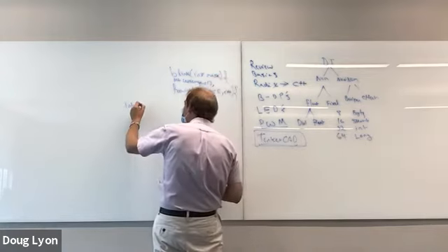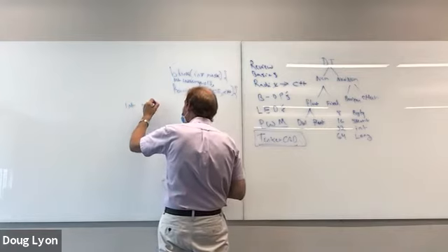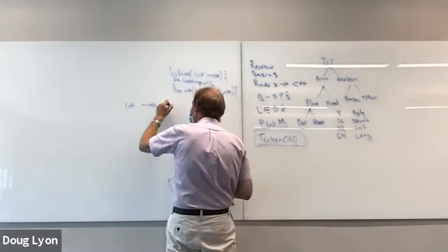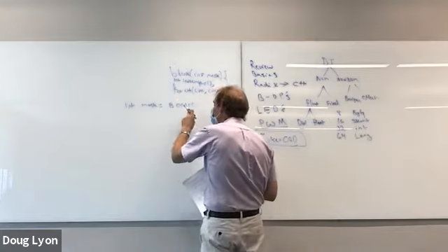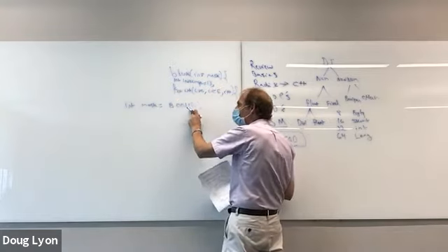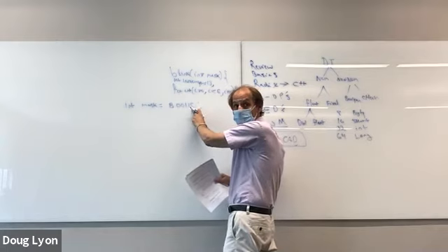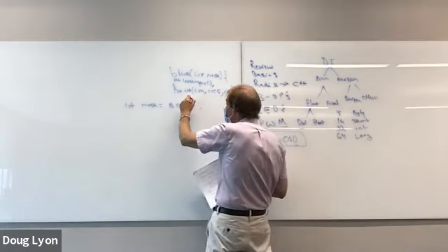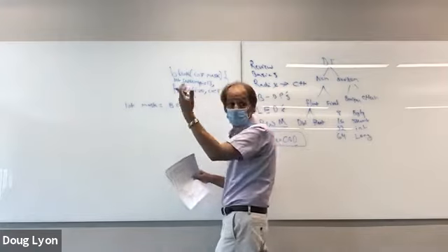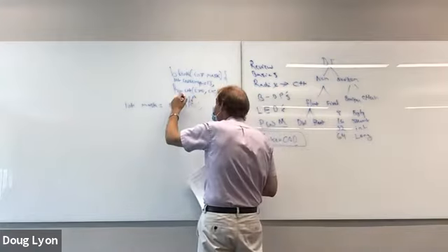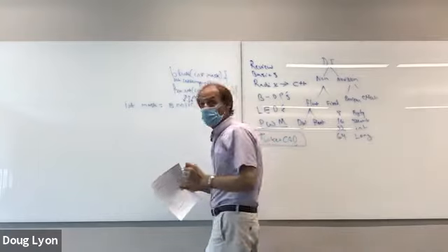So integer mask equal to binary 0, 0, 1, 1, 0 says these 2 LEDs are on and the least significant LED is off. If this is LED 13, this would be LED 11. If you remember, we're using odd LEDs. This would be LED 9, etc.